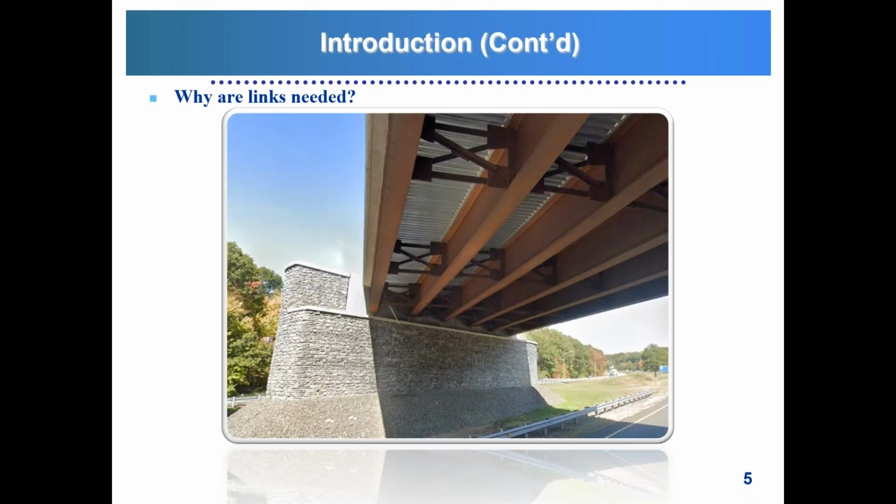So here we have a typical steel girder superstructure. And if we look at it the way it will look in a Midas model, essentially we're going to have beam elements for the main girders, and you're also going to have the elements and nodes for the cross-frame members. Now, these cross-frame member elements are at a different elevation from the girder nodes, from the girder elements. So at this point, the software doesn't know that they are connected, right?